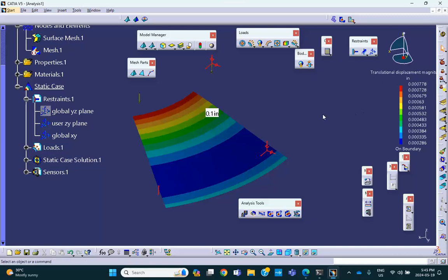0.00078. To find the stiffness, take the load, and the load is not 100. The load is 900, because it's 100 times 9 of them. This sector is 40 degrees. So there are 9 of them that go around the top edge. So the force to cause this displacement is 9 times 100. So 9 times 100 divided by that number is going to give you the stiffness of this bell spring. All right, folks? Good luck.